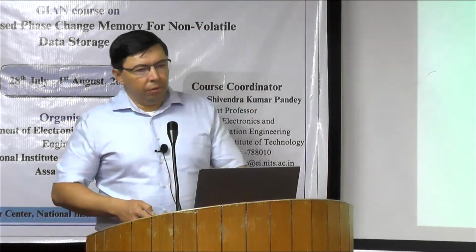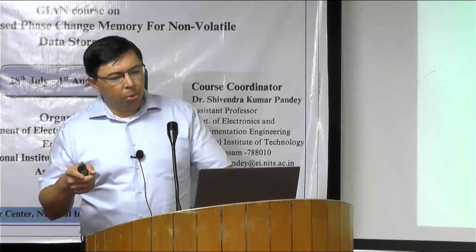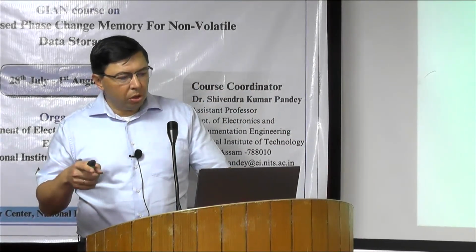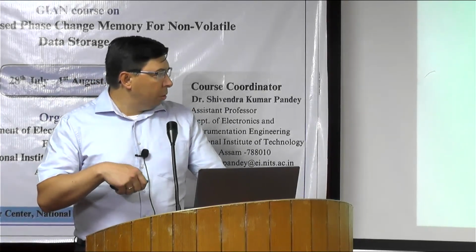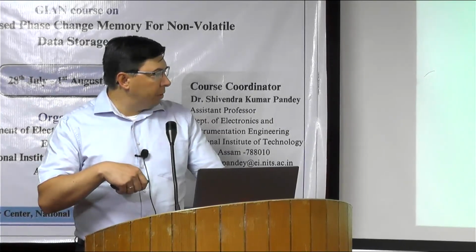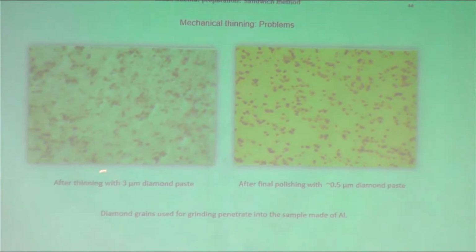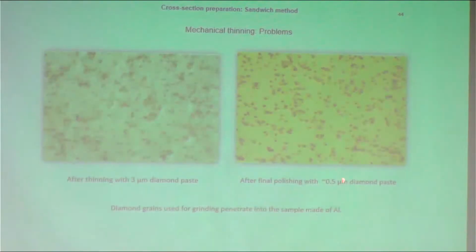If you use mechanical polishing, you use a special paper covered by diamond, or a paste with diamond. The grain size is several micrometers or less, like 1.5 micrometers.